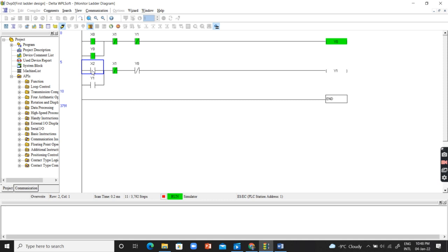If this would happen, it would put extra stress on the bearings of the motor. So irrespective of this student turning it on or off, your output is locked. It's interlocked and it won't allow you to turn it in the opposite direction. That's the protection for the motor which this ladder logic provides, right?